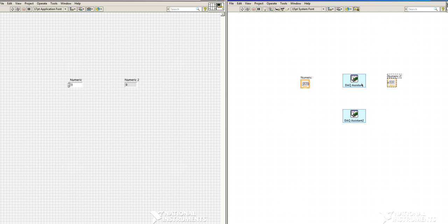And what I told you, I actually got it reversed. First myDAQ assistant, that'll be our output indicator. We're going to double click on the myDAQ assistant, the initial myDAQ assistant, acquire signals, analog output, voltage, AO0, OK and finish. That will be our outlet to the myDAQ breadboard.